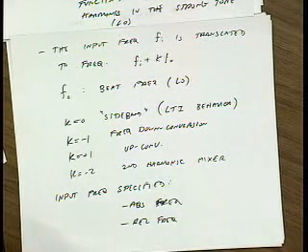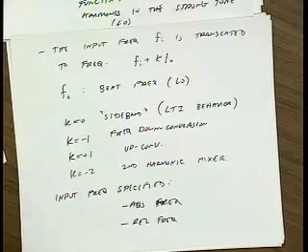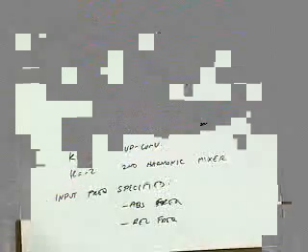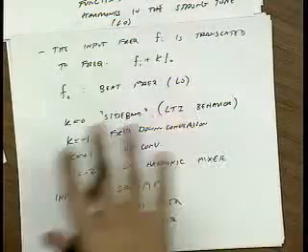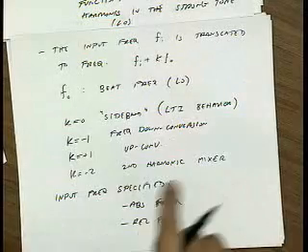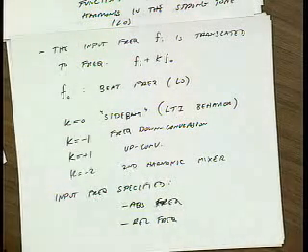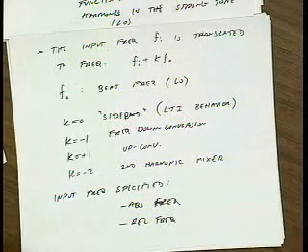Questions about PAC? Here's what I suggest: the first time you run PAC, run a very simple circuit that you've analyzed by hand, let's say a simple switching mixer, where you know all the right answers. You know exactly what the conversion gain should be to the first harmonic, to the second harmonic, and so on. Check it to make sure you're running it correctly. There are also some good examples that come with Spectre that you can try out. Okay.